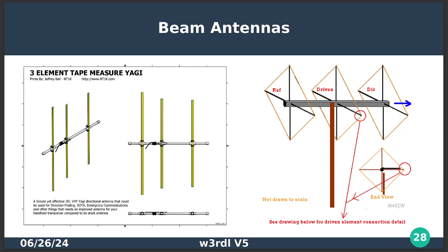How am I polarized right now? Horizontally. Vertically. Okay. Close by, with the radio signals that I'm getting when I use that, horizontal or vertical doesn't seem to make a lot of difference, especially with the radio that I have, because there's no signal strength meter on there. If I hear it, it's good. If I don't hear it, it's bad. But farther away or with weak signals, it would make a difference.